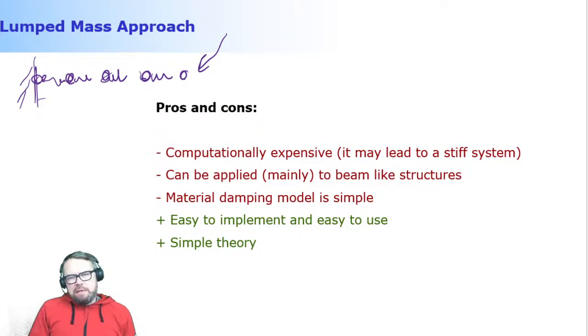The force for sure will introduce bending and some axial deformation. Now, if you have a structure that is very thick, or even if it is not that thick, it's pretty clear that the bending deformation is associated with low stiffness, whereas the axial deformation is associated with high stiffness.